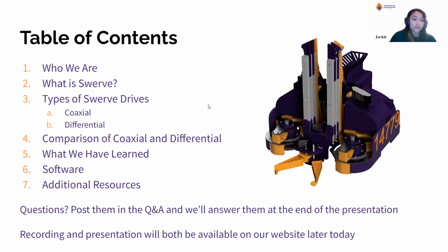The linear slides we use are the Misumi telescopic slides, and there are also other options available out there. If I recall, goBILDA has their own Viper slides as well. But our team chose Misumi, as they are both very fast and durable, and very solid when they're fully extended.